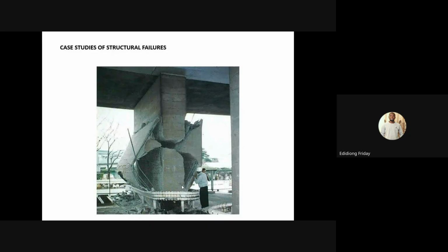So your decision as a structural designer has to be based on these analyses. Number one, we could retrofit. Number two, we could completely demolish and reconstruct. And I think those are the two options. And then the third one someone mentioned was to introduce another pier beside this in both directions, to the left and to the right, in order to reduce the load on this.